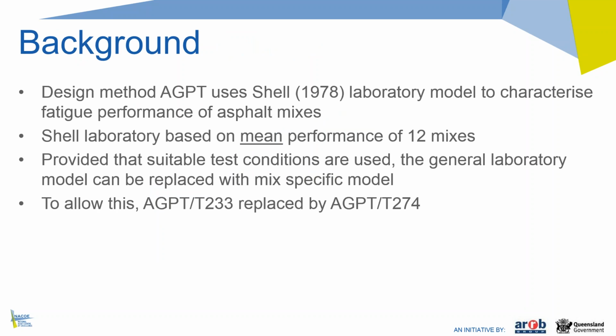Okay, so just to take a step back again to the argument. Why do we say that we can do this? The current design method of the Austroads Guide to Pavement Technology uses the Shell 1978 laboratory model to characterize the fatigue performance of asphalt mixes. That is based on the mean performance of 12 mixes, and provided that we use suitable test conditions, we can replace this laboratory model with a mix-specific laboratory model for a mix that we've actually measured.